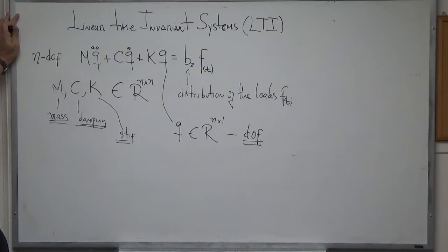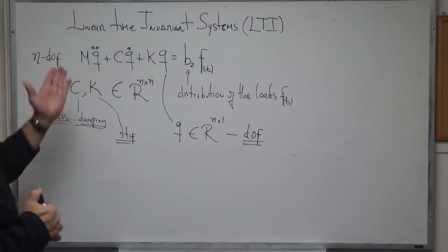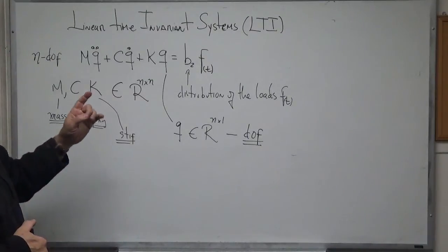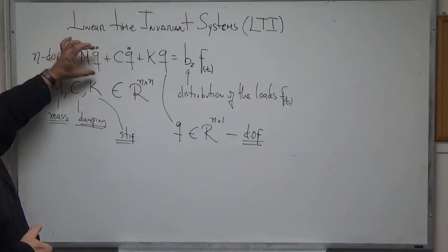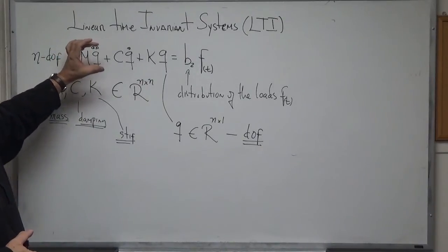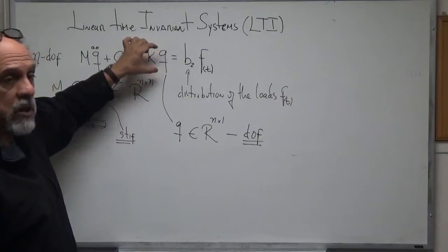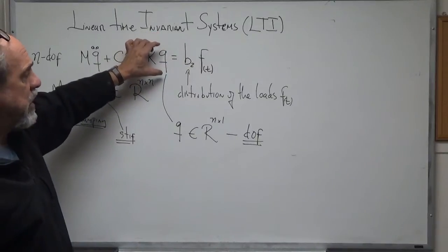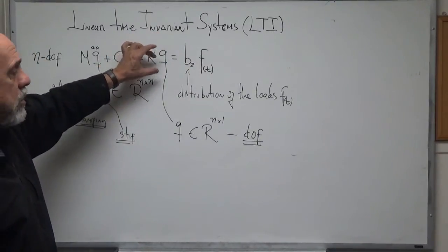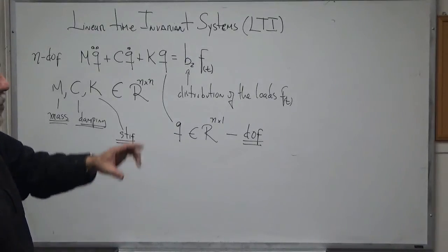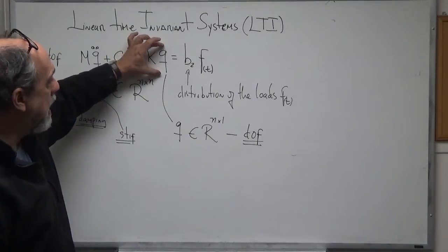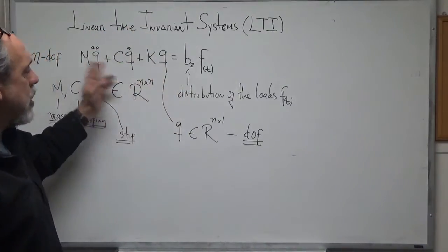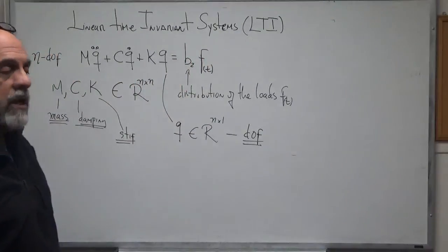So in the course in structural dynamics, we attempt to find out first how to formulate these equations and how to solve them, okay? In system identification, we actually want to measure some of the q's, obviously not all. That's one of the problems that a lot of times people have, is that they write papers in which you're measuring all of the q's. Well, essentially that's an academic problem. What you can do is measure some of the q's, unless you're talking about little simple things in a classroom. But if it's a real situation, forget it. So you can measure some of the degrees of freedom, and you can measure perhaps some of these excitations, right?